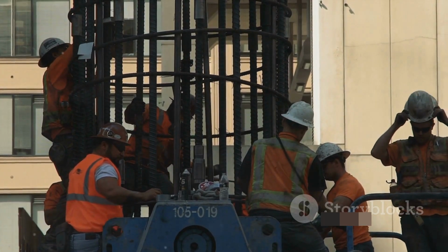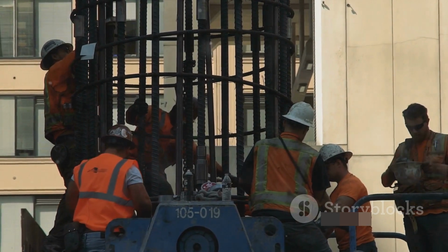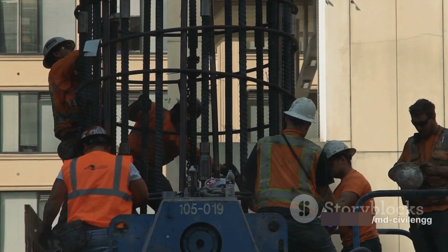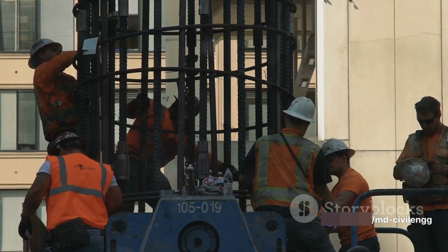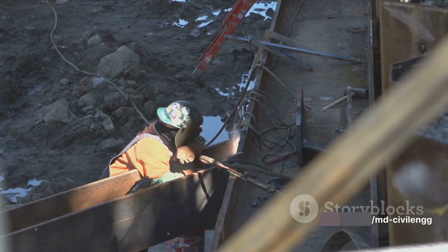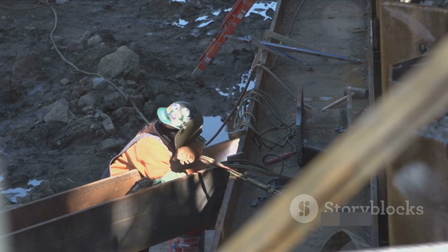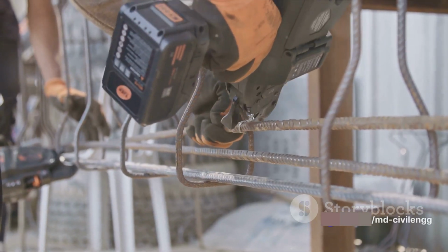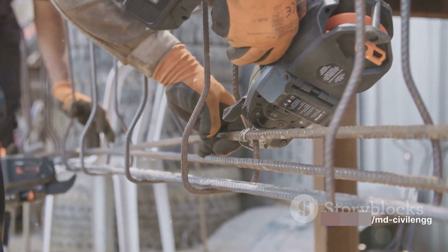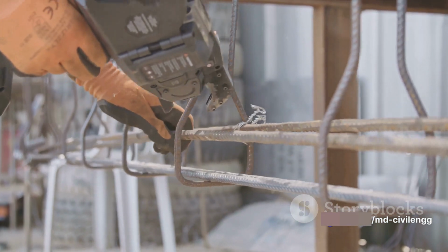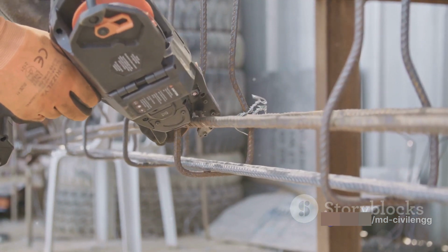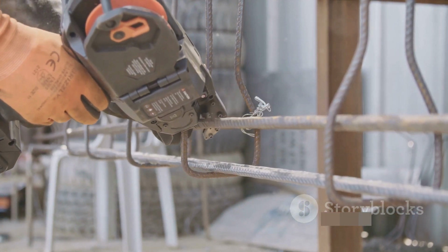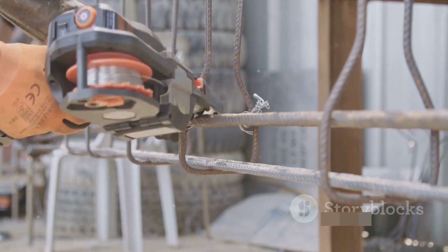The smallest diameter of the bar that can be used is 12 millimeters, and the maximum distance between longitudinal bars should not exceed 300 millimeters. Moving on to transverse reinforcement, which runs horizontally. The diameter of the lateral ties, represented by the Greek letter phi, is determined by the minimum diameter of the main longitudinal bar. The pitch, represented by the letter P, is the minimum of the least lateral dimension, 16 times the minimum diameter of the main longitudinal bar, or 300 millimeters.